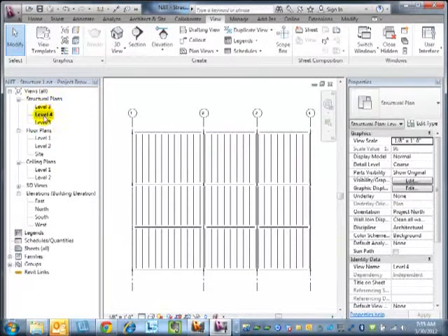Now, the 3D model. Since the copy is sort of a weak link, that wouldn't have fixed it. Copy and paste doesn't carry all the same relationships, as though the column had extended all the way up. Think about another way to do that. If I had placed the columns manually at level 3 and 4 on the grid, then everything would have moved.